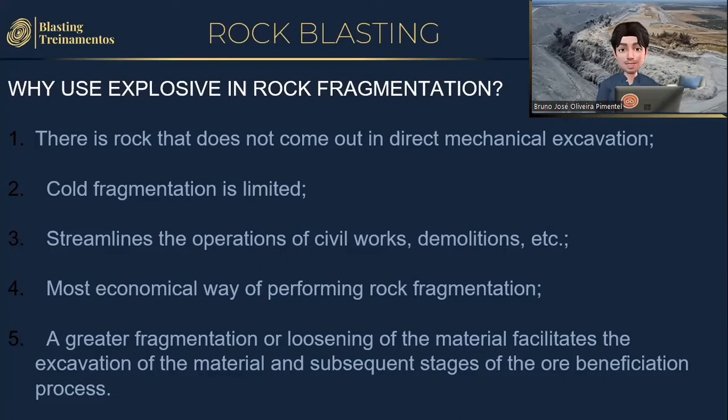Finally, we even have scenarios in which other processes could be used, such as direct mechanical excavation in a very soft rock, but even so, the use of explosives can provide better fragmentation and loosening of the material, and this allows the excavation and transport of this material to occur more efficiently and faster, as well as directly contribute to the rock processing steps.